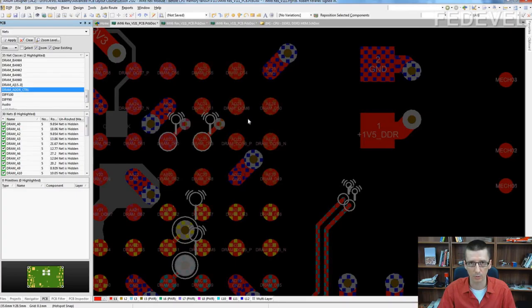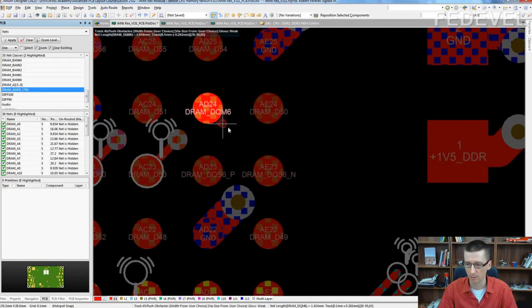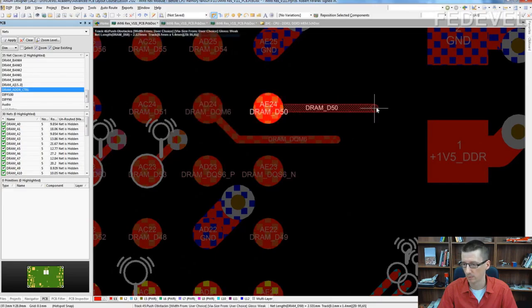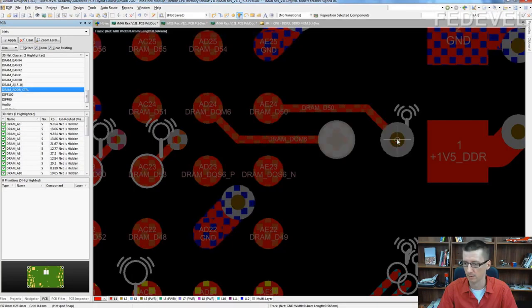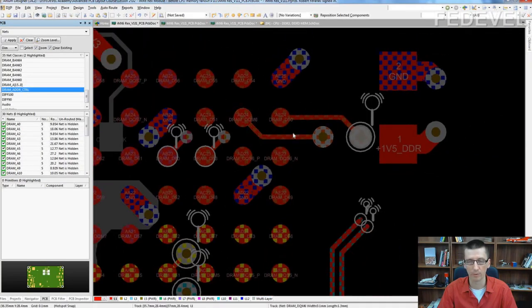If your design is not using micro vias, only through-hole vias, what you really may want to do is fan out these two rows of the processor or BGA away from the BGA. So do it something like this. Go here and here, go here and here, and place the vias away from the processor, so you have some space here.